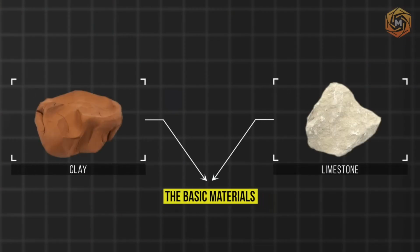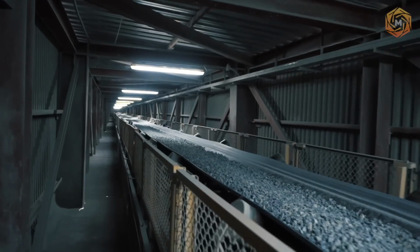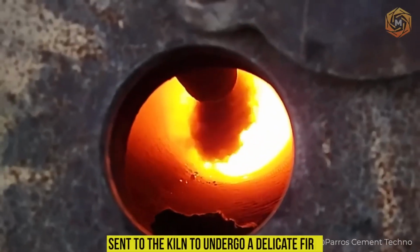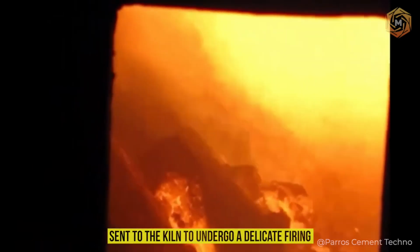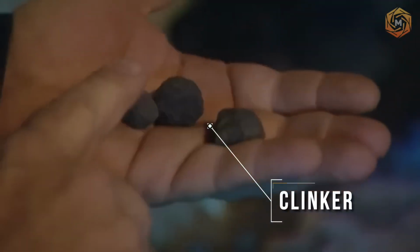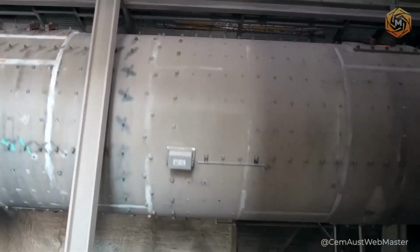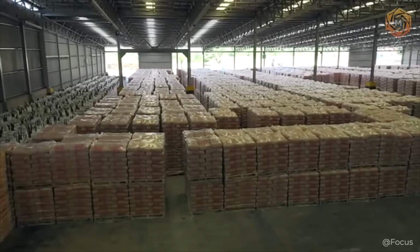The basic materials, clay and limestone, are taken and then crushed with special equipment. Having obtained a powdery material with the help of pneumatic tools, it is sent to the kiln to undergo a delicate firing. The clinker, which is formed after this complex process, is crushed to the specified fraction, packed into prepared containers, and transported to the warehouse for further storage.